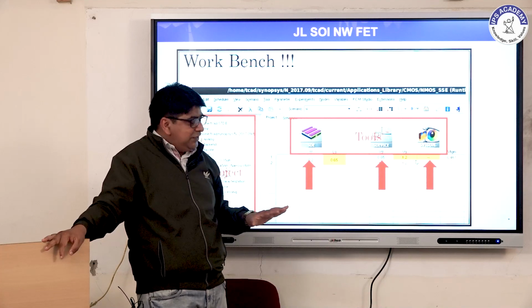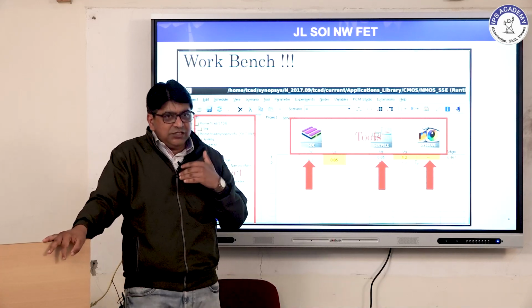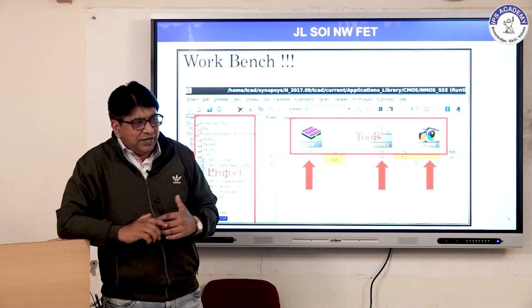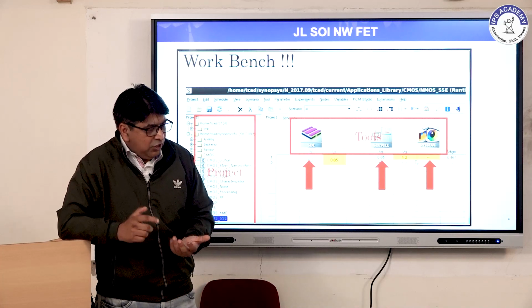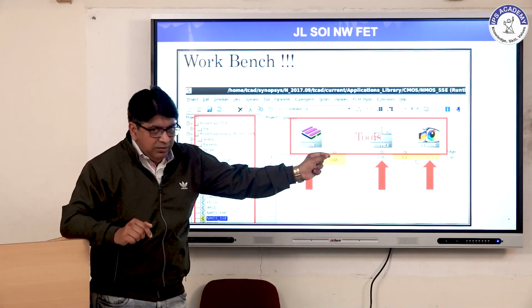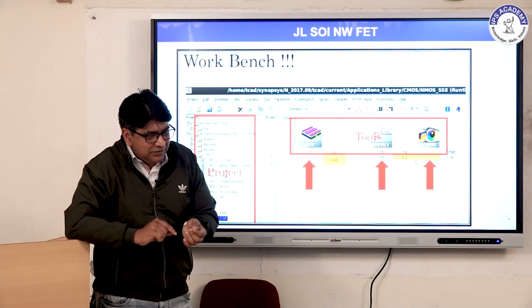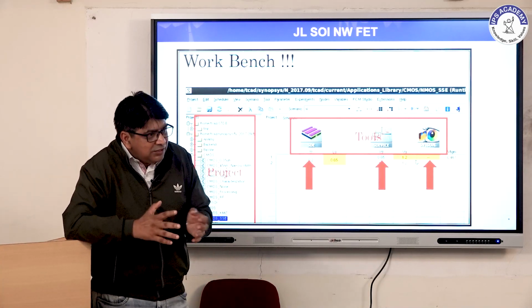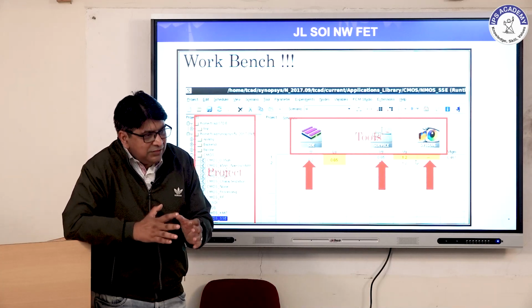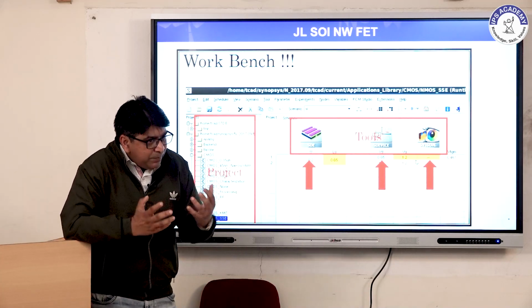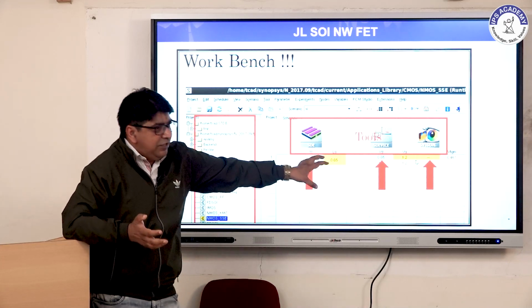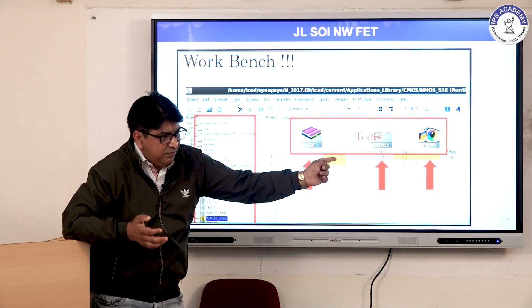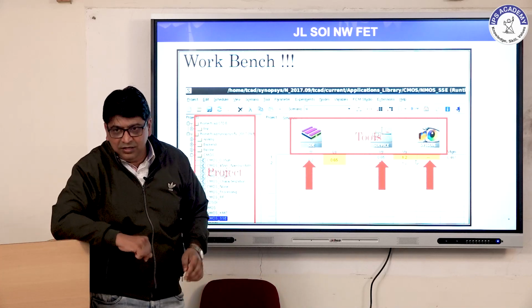Once you develop the device, you just generalize, you can place the device dimension on a parametric basis. You just select one particular parameter, like device channel length, oxide, or doping. These are the device parameters. Once you design the device in terms of parameters, the parameters will reflect here. You select one particular parameter and you can start checking the simulation.